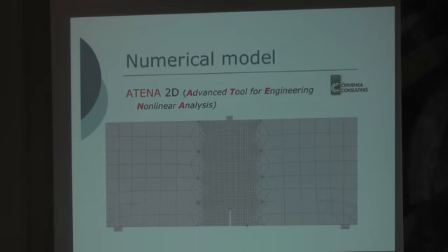Okay, now the creation of the numerical model. As I told you, we chose a commercial finite element nonlinear system which can predict the fracture behavior of our models. It is based on the orthotropic theory of smeared cracks with the implemented crack band model, so simply the cohesive crack model was implemented in the software. It consists of various nonlinear material models like plasticity, fracture and damage.